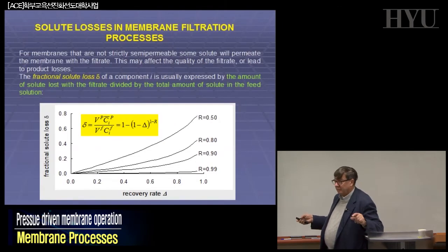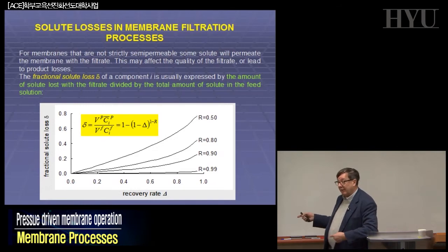One way to plot your experimental result that can be useful sometimes is this: it's difficult to operate with a membrane with 100% selectivity, or even 90% selectivity. So you always lose some of the solutes in the permeate, and you want to know sometimes how much of your solute is lost. Due to the fact that the membranes are not 100% semi-permeable, as we defined before, the quality of the permeate is not 100%.